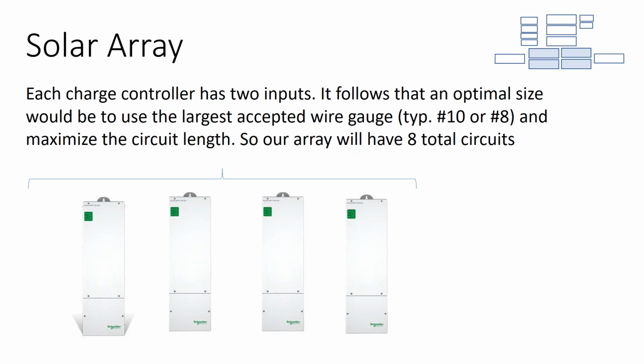With batteries, particularly if you have more than 1 circuit of battery, if you have different resistances in each circuit and your batteries are being wired in parallel, what that will do is it'll cause the battery with more resistance to degrade faster than the others, and that'll have cascading effects down the line.